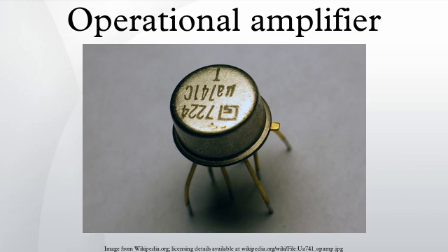Input current. Due to biasing requirements or leakage, a small amount of current, a few nanoamperes for JFET input stages, and only a few picoamperes for MOSFET input stages, flows into the inputs. When large resistors or sources with high output impedances are used in the circuit, these small currents can produce large unmodeled voltage drops. If the input currents are matched, and the impedances looking out of both inputs are matched, then the voltages produced at each input will be equal. Because the operational amplifier operates on the difference between its inputs, these matched voltages will have no effect.